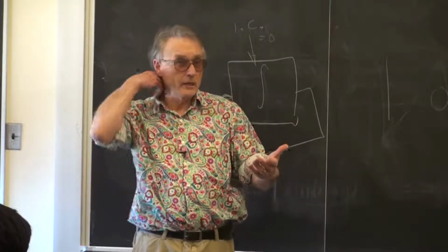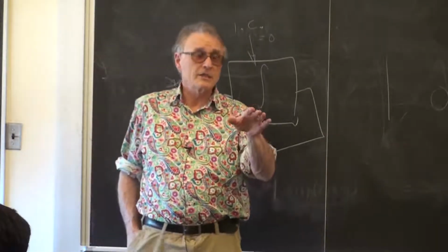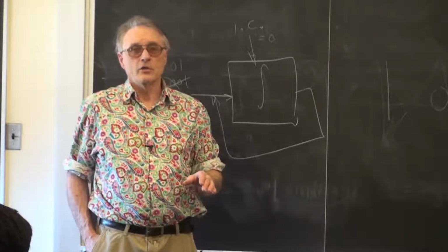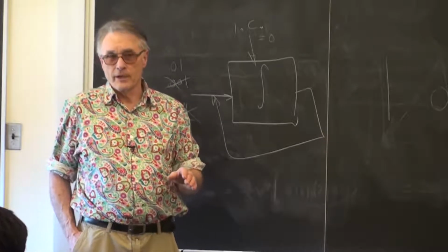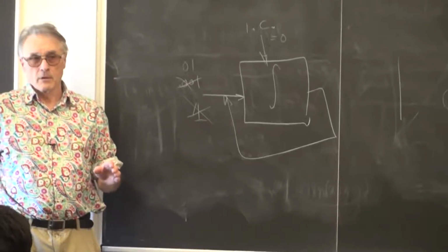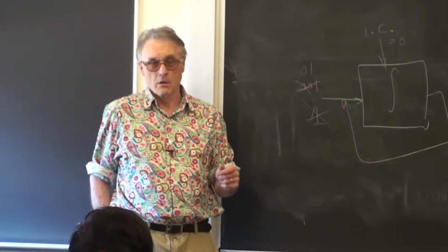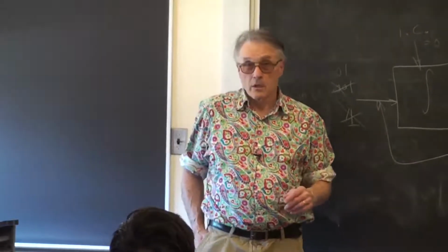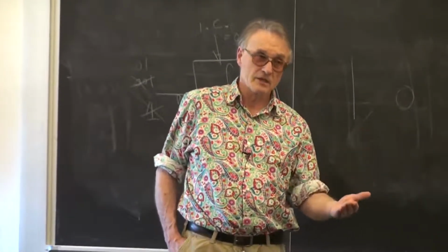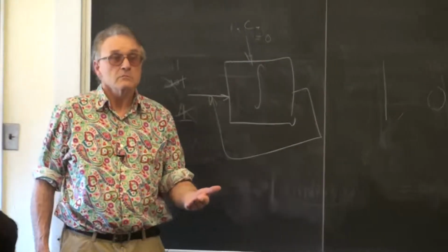You attach an interrupt and it does something which is kind of interrupt-like, but it's not a hardware interrupt, so the latency is rather long and variable. I don't know of anything here that would do that. My inclination is to say that if you need really fast response for something, put it in hardware rather than put it on the HPS.